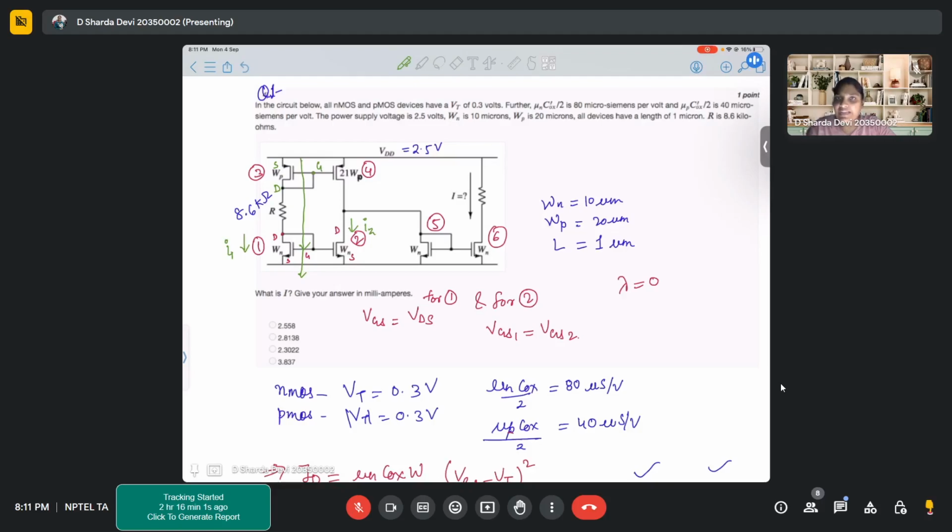So maybe you can analyze that one by one, transistor by transistor: how VGS is changing, how VDS is changing. Then when you know the currents, you can find the GMs, and then you can see how GMs are changing, whether they are changing or not, which factor is affecting what. It is ultimately about the analysis because you know how things work, what the formulas are, everything you know. It's just that now you have to analyze the things. That's it. Nothing different. Sure, I will amend. Yeah, that is the case.